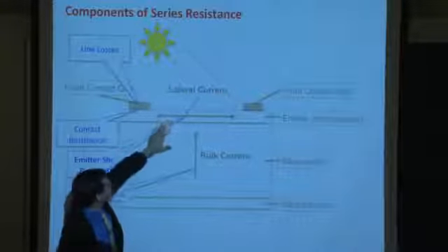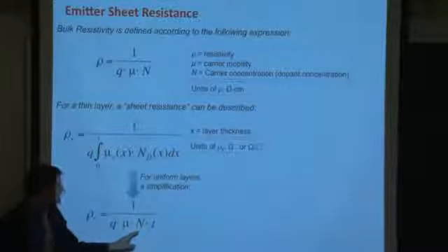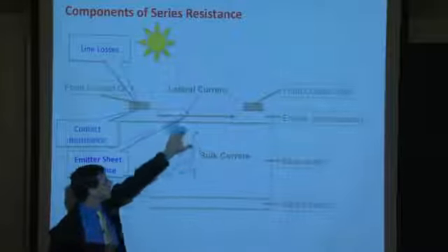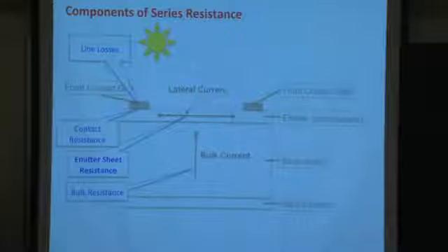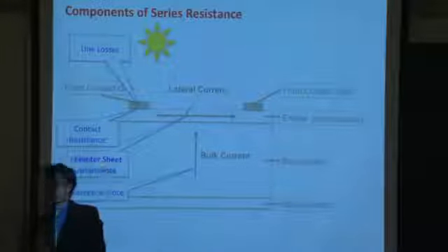And maybe the current collection probability from that layer up here that has a very high carrier density is not going to be as large. In other words, the current collection efficiency won't be as large as if I generated the carriers here in the bulk because of an effect called Auger recombination, which we'll get to in a few lectures. So this front surface region here oftentimes is considered a dead layer to a solar cell.